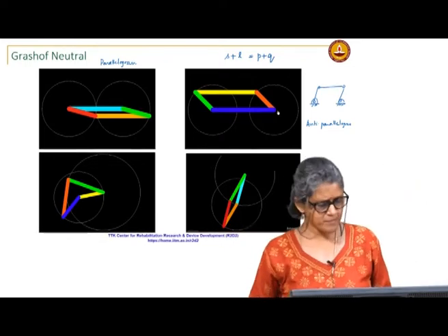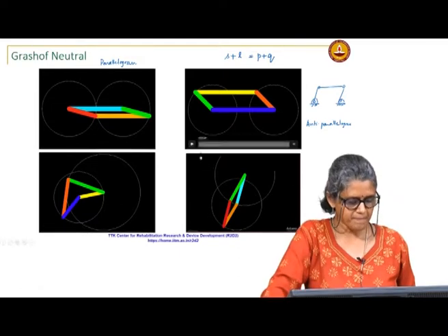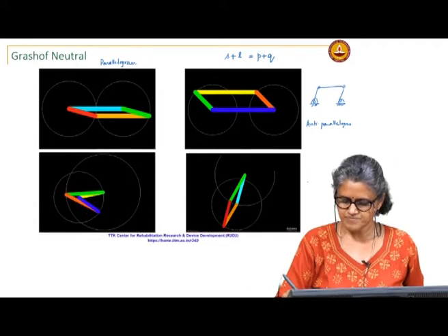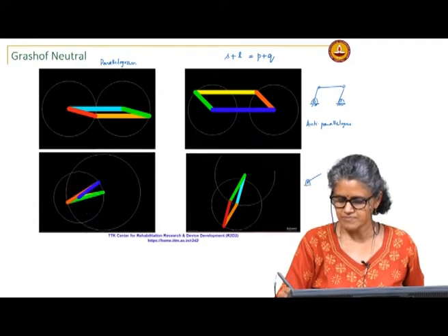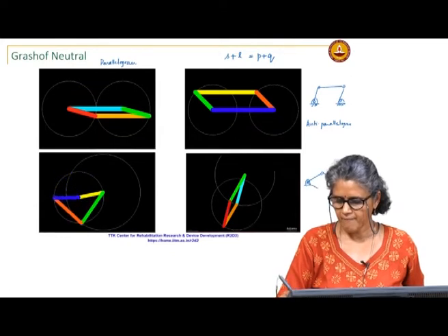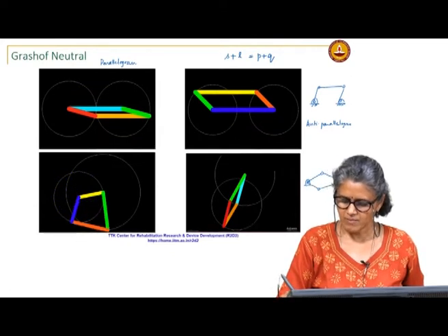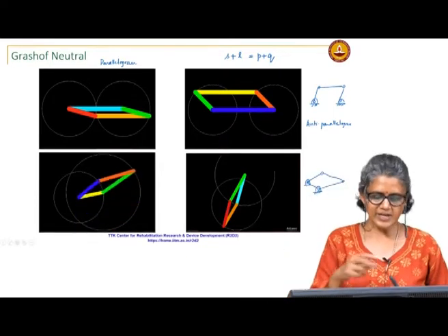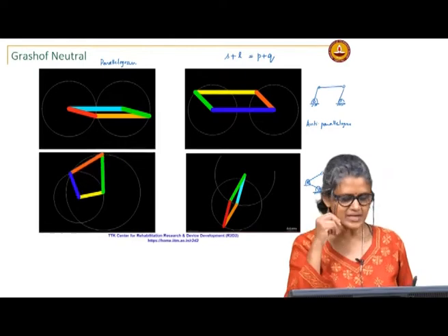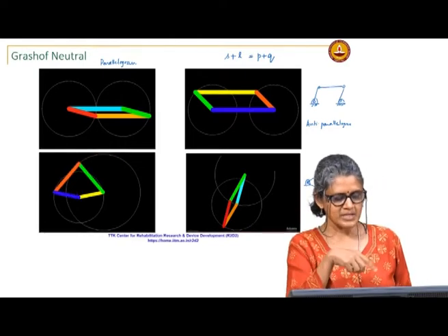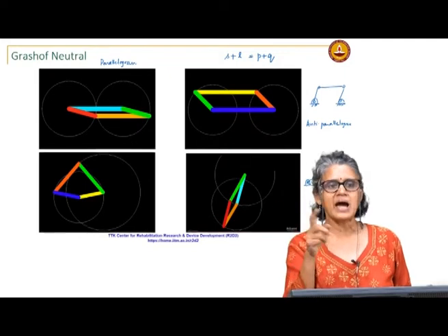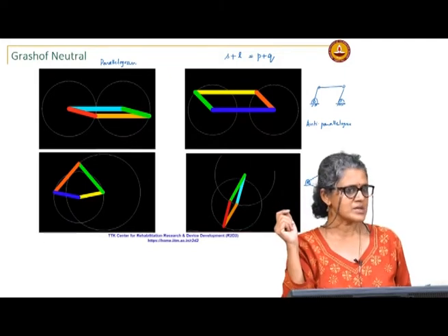The other form is the kite form, where you have the two short links. So, it is like this, or it could be the other way. That is called the kite form, it looks like a kite. And here, the speed of the output motion will be half that of the input motion.